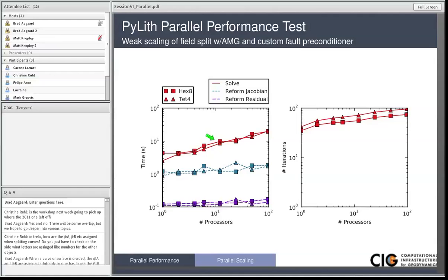We were using the ML Trilinos implementation for this particular case, so we can switch and try one of the other algebraic multigrid algorithms within PETSc and get feedback from the rest of the PETSc development group besides Matt to see how we can improve and where the bottleneck is in terms of the scalability of the algebraic multigrid preconditioner. But in general, we're very pleased with these results, and we expect that even on larger problems, we get similar types of performance.